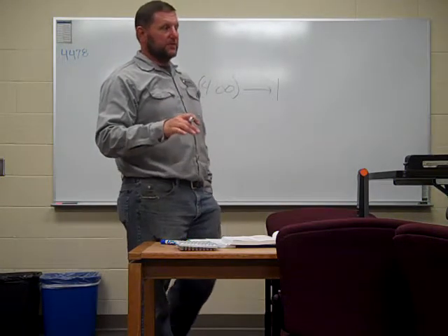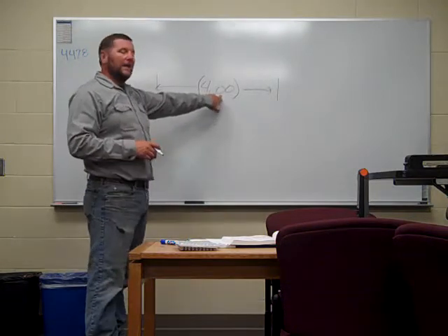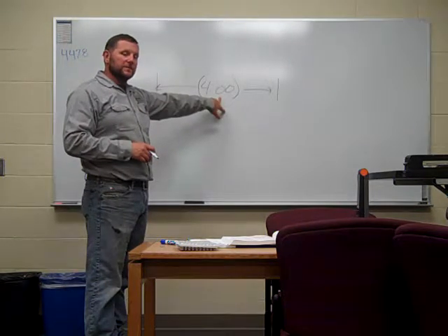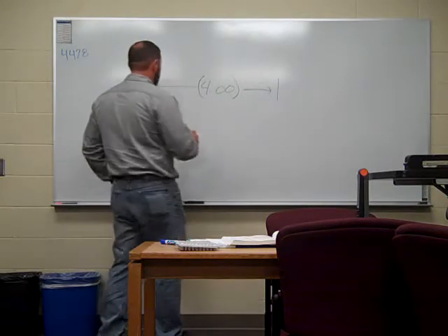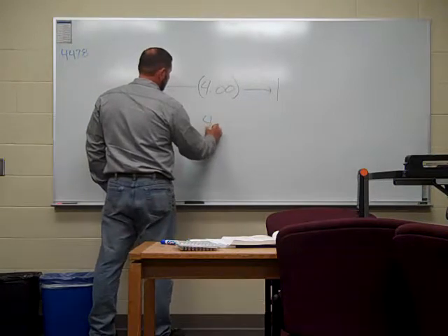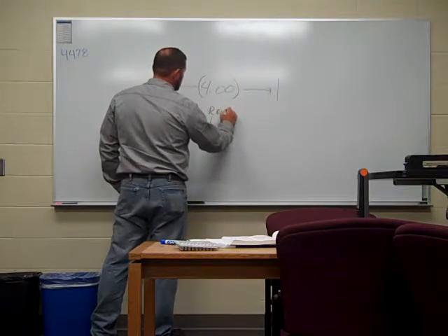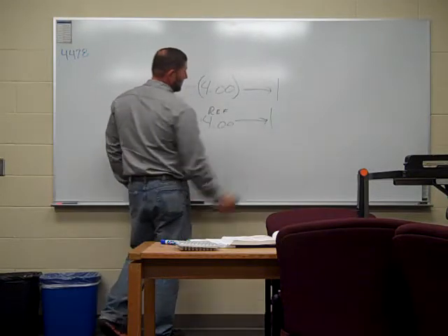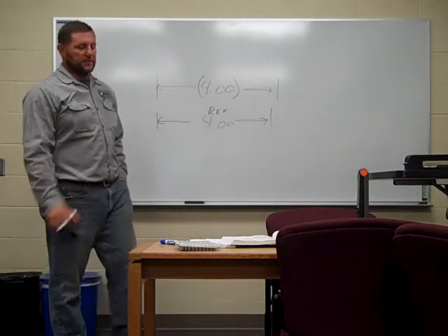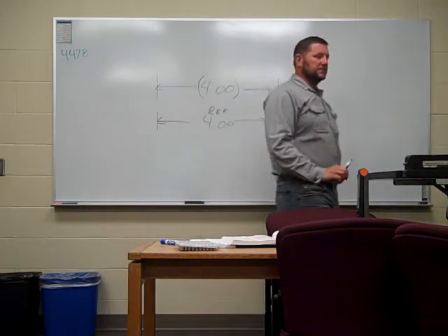A lot of engineers use that when they're calculating the amount of steel they're going to use. So tolerances do not apply to a reference dimension. It's given to you two different ways. In parentheses, or it might be 4.00 with REF alongside it. Those are telling you that it is a reference dimension. So tolerances don't apply to reference dimensions.